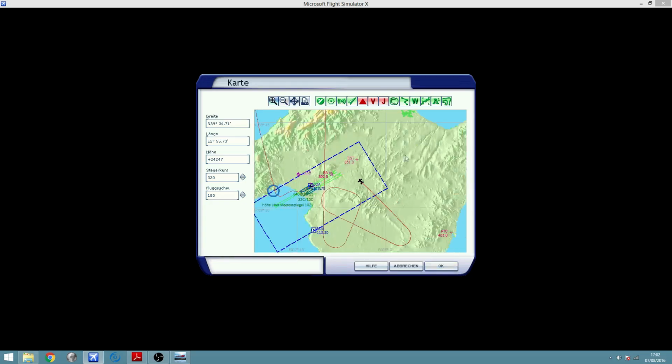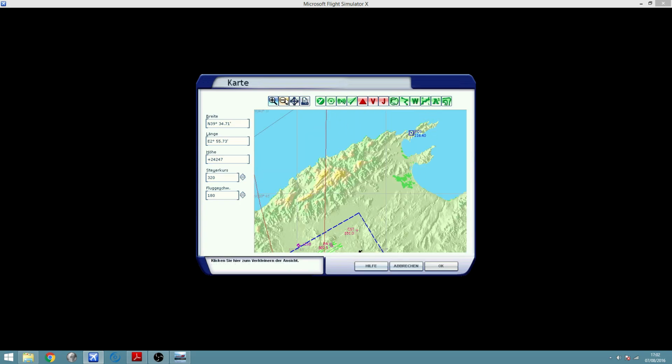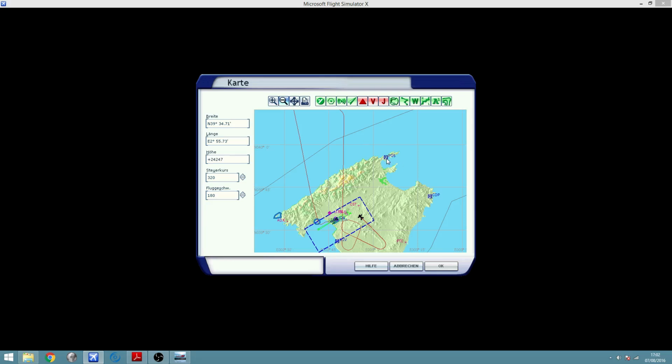So here is the Papa Oscar Sierra VOR, and radial 180 would be completely to the south, to the magnetic south of Papa Oscar Sierra. That's where we were, and we are flying on this track looking for the 225 radial, which should be something like this. And once over this radial, once we cut this radial, we will turn right towards the station. That's what we are going to do. I'm looking for radial 225, which is ahead of myself currently.